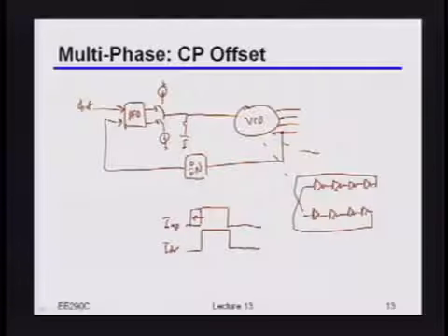Okay? So it turns out the way you can actually do this is quite clever. If you want to intentionally introduce an offset, you just intentionally skew the up and down currents. So in this particular example, whatever CDR control bits you had, you would use those to program the down current relative to the up current.